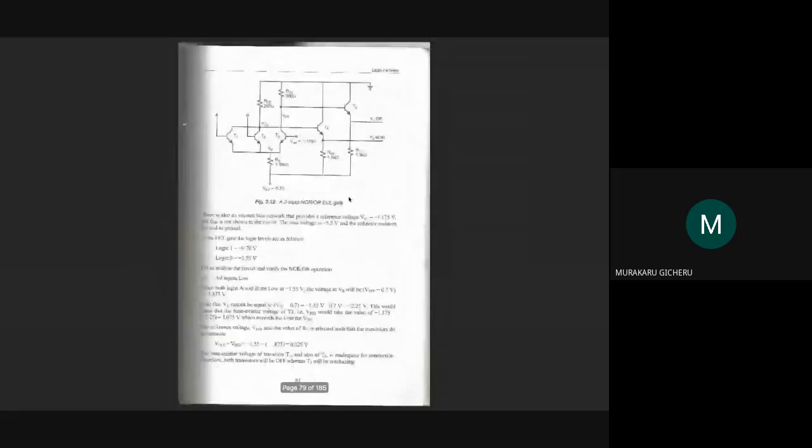They will range from different values because these devices are not perfect. Even for TTL, you'll find, you know that diagram for logic levels? Let me see if I can find it here. So you know this diagram at the top, figure 3.4. This is a good example of how whatever logic level you have is not going to be fixed at one value. It will have a range.